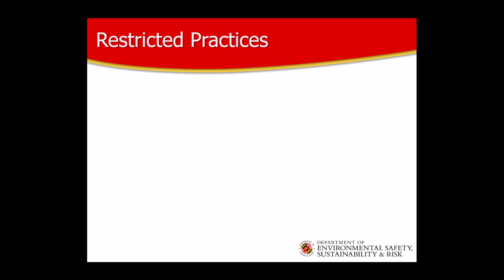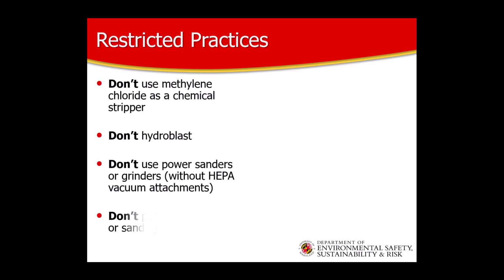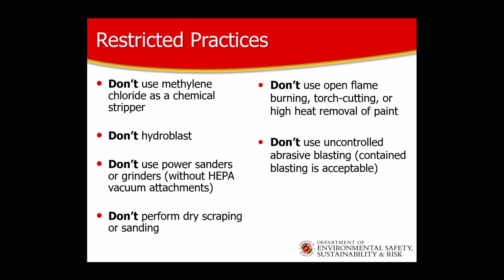Because we work in environments where lead is present, we also need to know the restricted practices involved with working around lead. Practices such as open flame burning, torch cutting, or using machines without the proper attachments to collect dust can be dangerous work practices.